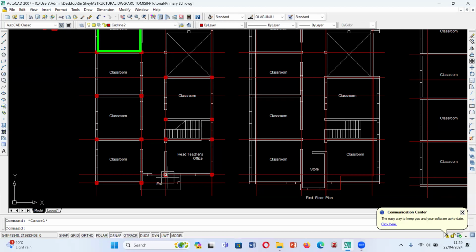Then while you are gridding and paneling, some of the things that need to be running in your head are, number one, the wall alignment, the window openings, door openings, any other open areas, then the best, safest and also most economical way of designing any panel you want to design. Those are some of the things that should be running in your head.